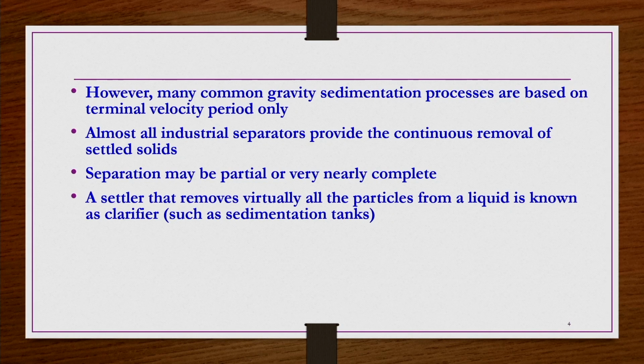Under this settling velocity, or settling by gravity, based on those principles we can design two kinds of equipment in which different types of separation of particles take place. One type is a settler tank that removes virtually all the particles from a liquid, known as a clarifier, such as the sedimentation tanks.